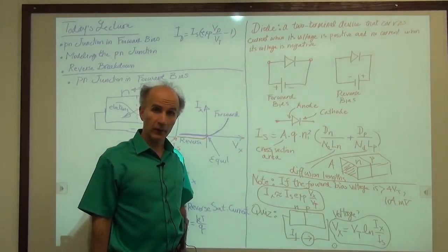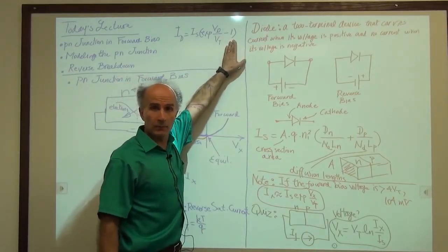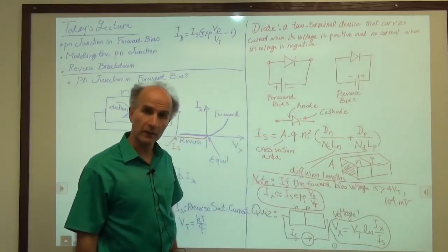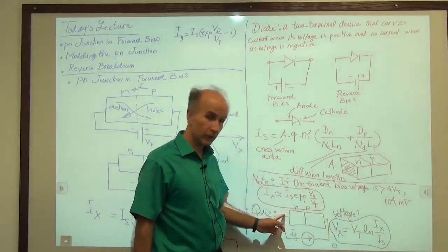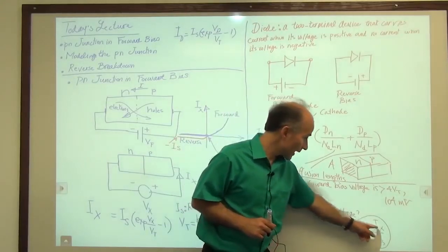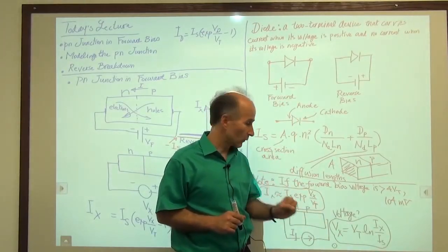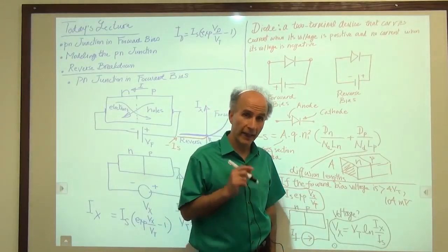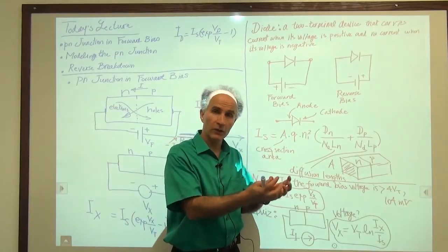So that's also an important equation. You have to remember both this equation, now without this one most of the time, and then this equation, again without that one. And this equation says that the voltage that you measure across a junction when it is forward biased and it carries a current of Ix is given by log of Ix over Is multiplied by Vt, 26 millivolts. Keep in mind that Is is constant when we buy that PN junction.